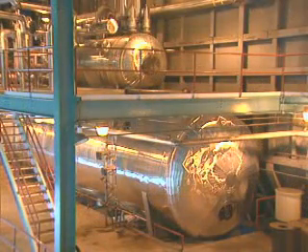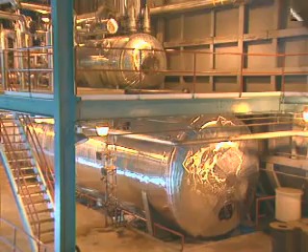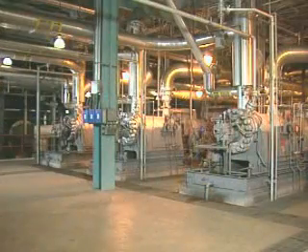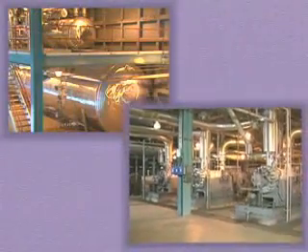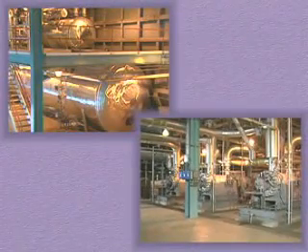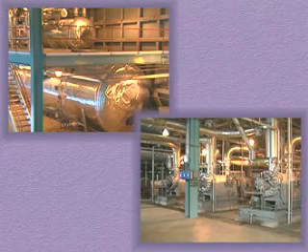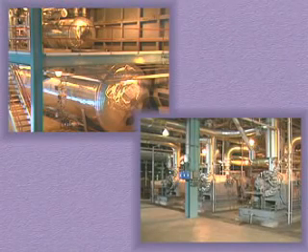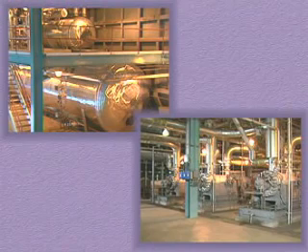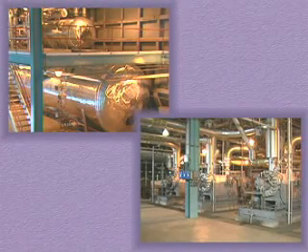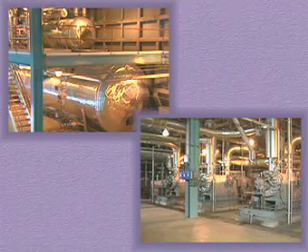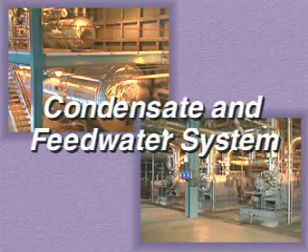Condensate from the main condenser goes through the condensate system and becomes feed water that returns to the boiler through the feed water system. In this way, the condensate and feed water systems work together to supply water at the proper rate to support normal boiler operation. Because the functions of these two systems are interdependent, they're often considered one system, the condensate and feed water system.